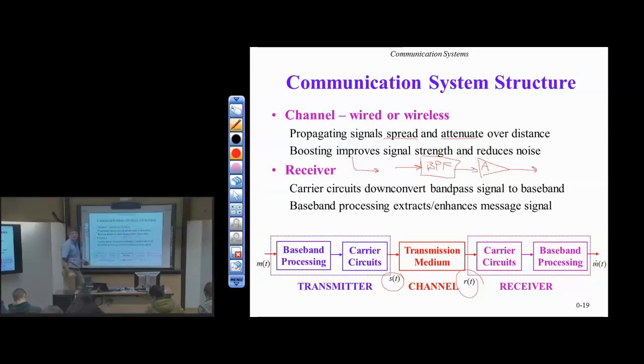Go ahead. Wouldn't the amplifier introduce more noise? That is correct. So you want to design this amplifier so that over the transmission band you don't get any bizarre effects. So you could decide to switch the order, which would make a little more sense, because otherwise I'd have to put another bandpass filter here. So we could do it instead. Put the gain and follow that by a bandpass filter.